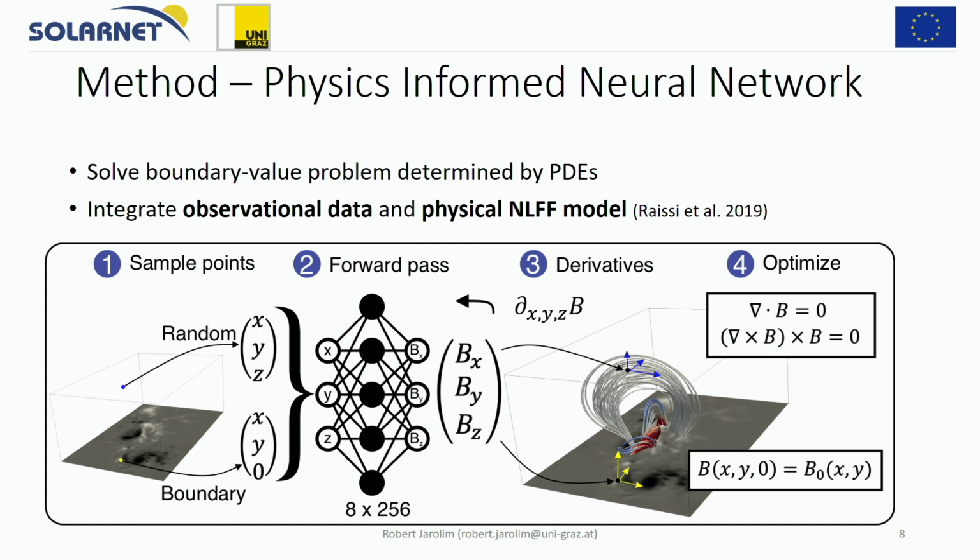Basically, the primary constraint is given through the disagreement between the boundary condition and the physical model. It's not the resolution that is limited here in this case. In the end, when this all is trained, it is all mesh free, and we always go back to the original magnetic field, right? So by just taking points in the simulation volume, sampling each of those points point by point and then constructing our solution from this, which we can then compare to something that is mesh based. Right, so this of course then takes more time because then we have to sample 8 times more.